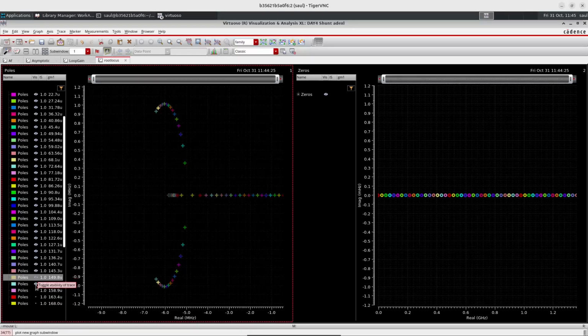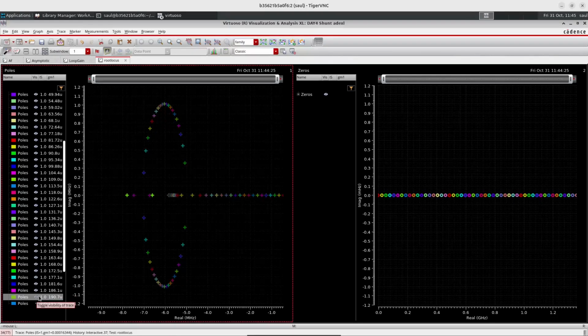And then we see that there was a phantom zero. We cannot see the zero here, it was somewhere here. We have the phantom zero here, and then the poles are being manipulated by this phantom zero. So they go around, they crash again in the origin, and then they split. One goes to higher frequencies, the other goes to lower frequencies, until they rest in these positions.